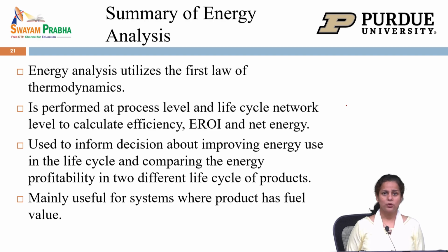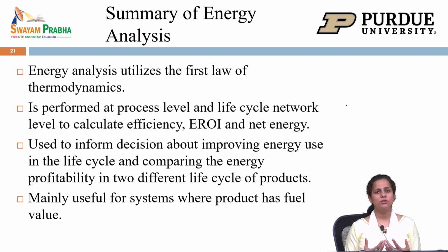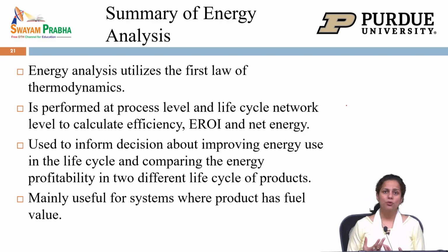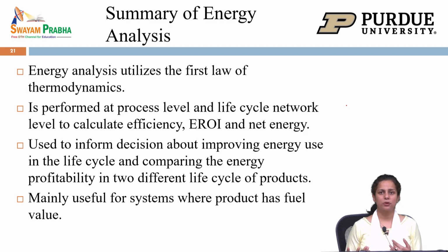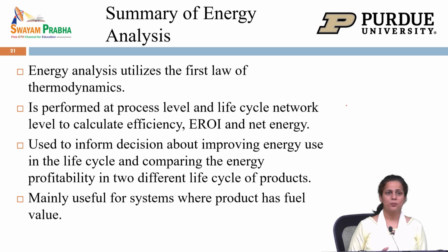So, you will hear this word energy return of investment a lot in the analysis of energy systems, where we want to know how much energy at the life cycle scale we have used, such that in the last example we saw that we have used about 29 megajoules of energy for processing for meeting the final demand, and then you can calculate what your EROI is for that particular processing energy. We can use this analysis to inform decisions about improving energy use in the life cycle and also comparing the energy profitability of two different life cycles of products and even energy systems. And this is mostly useful for systems where the product has fuel value.